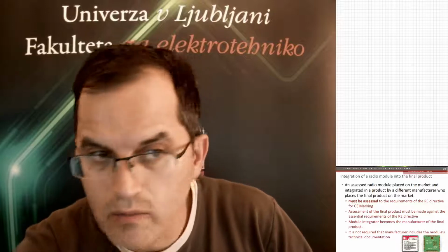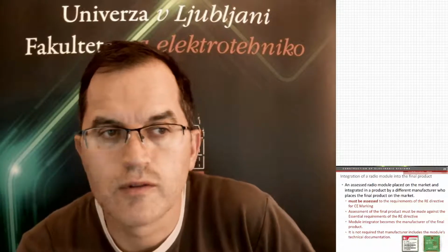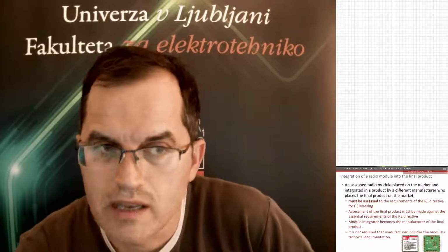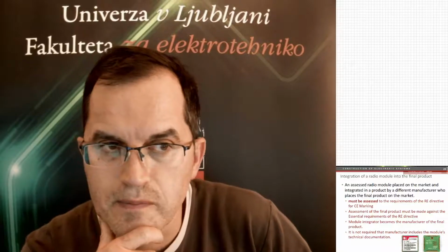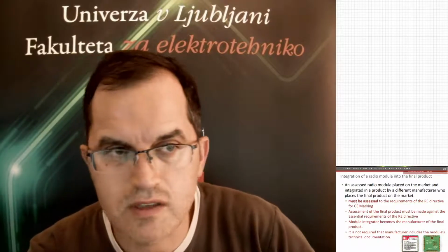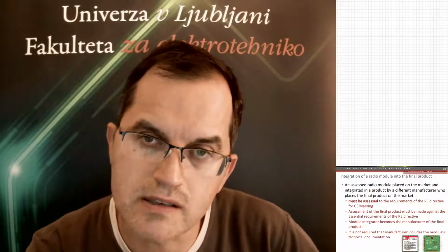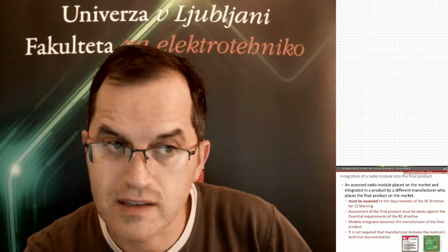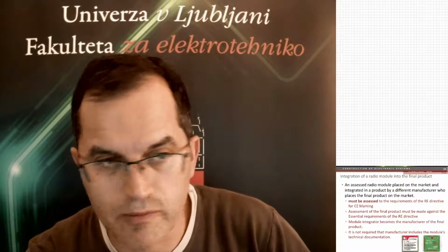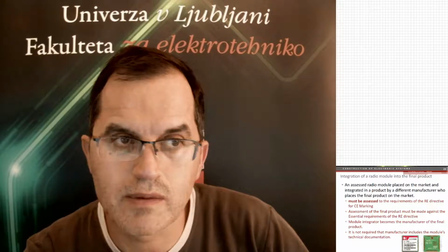You can make your own wireless interface, everything from scratch, and you would have to do the same amount of conformity testing. The other option is, of course, getting a certified module that already has all the tests. It's expensive, but then you can do less testing before the production, and for lower quantity production, maybe that pays off.